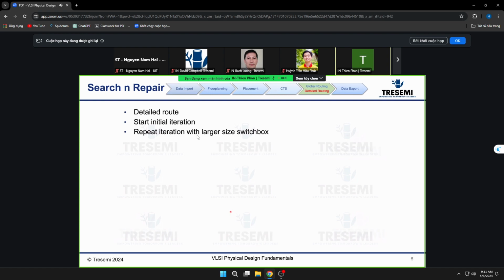So essentially it has to give up. It looks at the cost function, right? Time versus the quality of result. As I said, on an easy design, it's going to finish with very much the result that you want. Everything clean, timing, power, all those qualities met. So ultimately there's no need for post route optimization, right? But on a challenging design, you can have violations, and the tool can't keep iterating forever. So it has to stop.